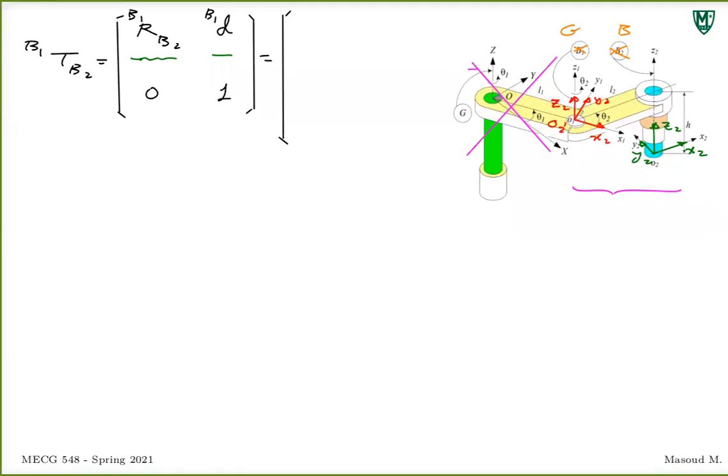how did we go from the global frame, which is B1 in this case and is fixed, to the red x2, y2, z2, which is the beginning of the motion, to x2, y2, z2 green? And remember, when we're talking about transformation, I said you always do the rotations first and make the translation later.